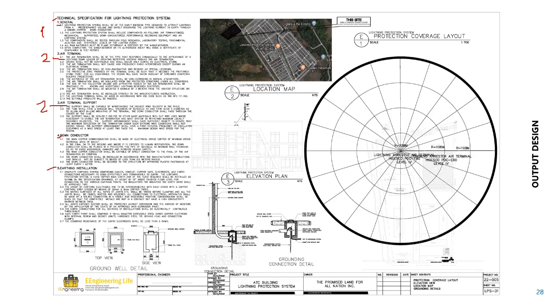Then you should have the details, the protection layout, and of course the location. That is important, because if you do the risk assessment, you need a location so that you know the lightning strikes per day and per year. So you will be needing it to do a risk assessment. That's why you need a location map, a specific location.